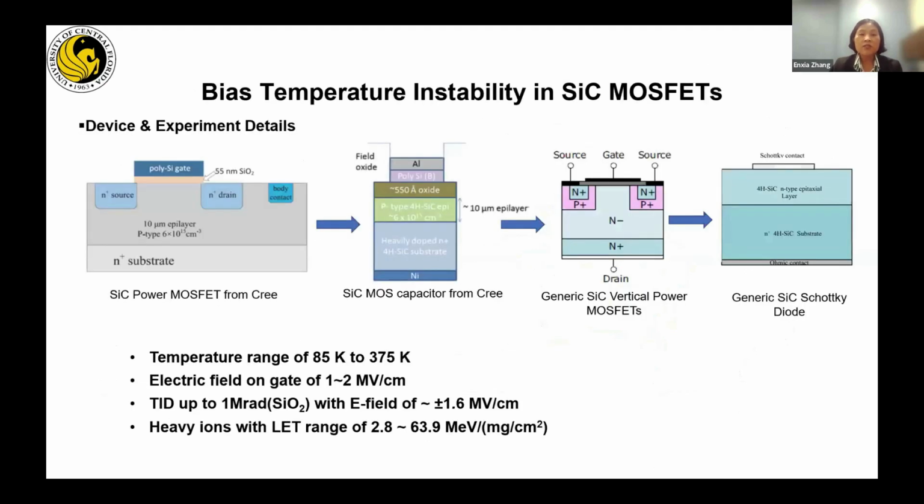From my research on silicon carbide devices, we started from the basics of MOSFETs and studied the basic mechanisms on the first generation fabricated by Korea, then moved on to the vertical power devices with the super junction or the charge balance devices from GE.